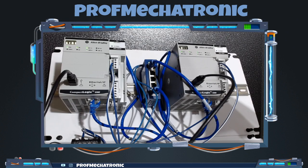This is because we've actually got communications between our PLCs, right? So we've got net A1 on both cards solid green, which means that they've got good connection between each other. And we've got our links pulsing, doing the communications between those two. So that's a really good sign as well. So now you're able to look at your hardware and really use those LED lights for troubleshooting purposes to be able to see kind of what's going on and how that functions.